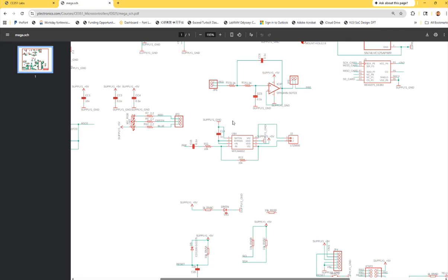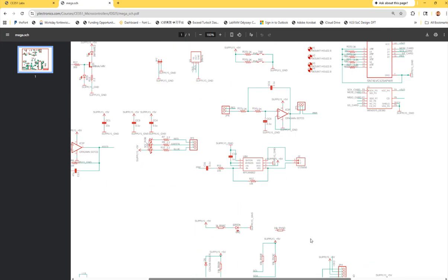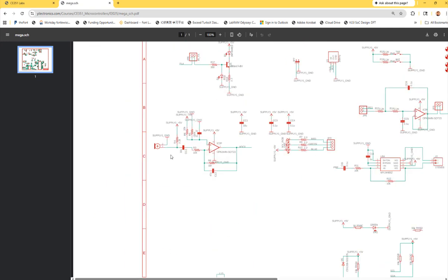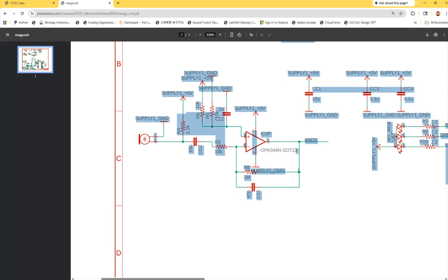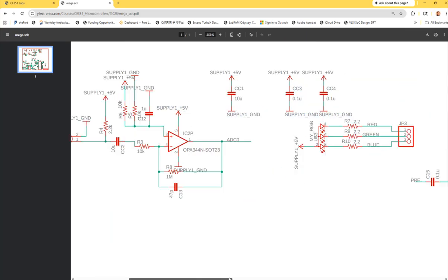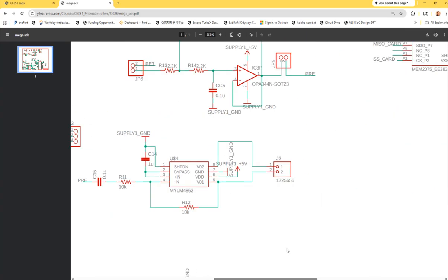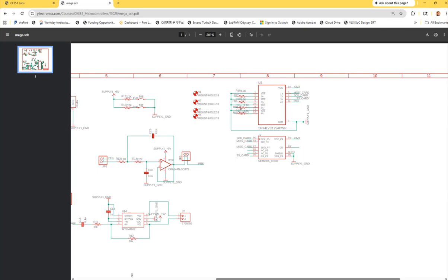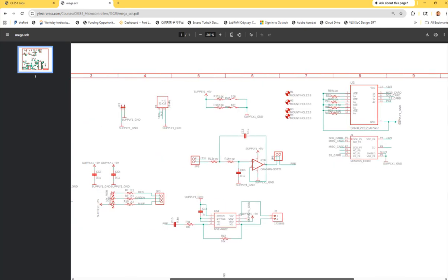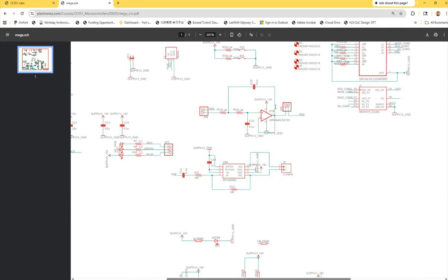So, for your audio amplifier sampling, it's over here. So you need to use this module for sure. As the module is shorted to ADC0, you have to digitize it, right? So, no doubt on that. And when you play it back, you will need these two modules over here, the IC card. You need to store it over there and then play it back. And also you'll need an audio amplifier and low pass filter. You need this guy and this guy.